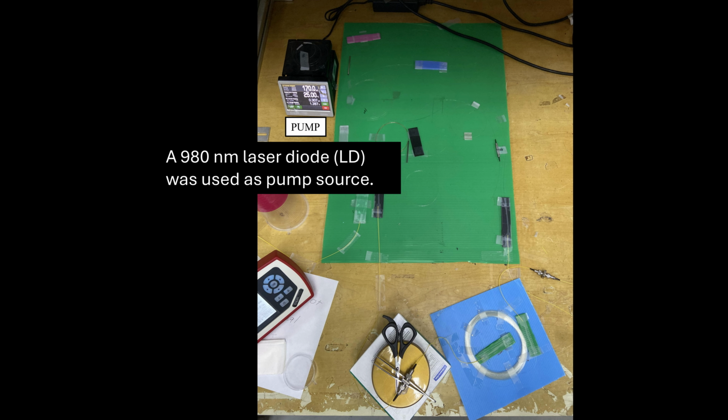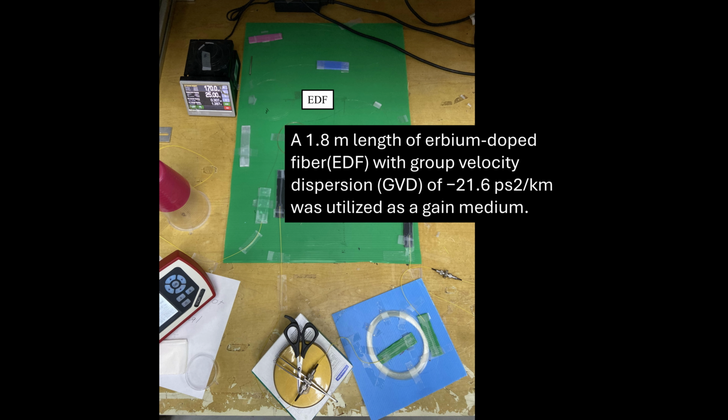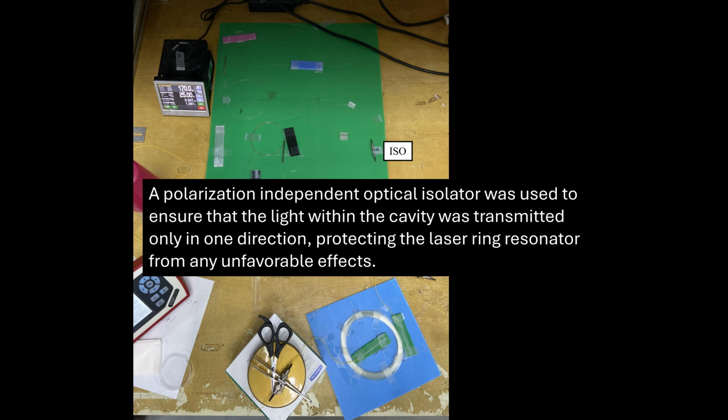A 980 nanometer laser diode was used as the pump source. Subsequently, through a 980 to 1550 nanometer wavelength division multiplexer, the pump energy was introduced into the cavity. A 1.8 meter length of erbium-doped fiber with group velocity dispersion of 21.6 picosecond squared per kilometer was utilized as a gain medium. A polarization-independent optical isolator was used to ensure that the light within the cavity was transmitted only in one direction, protecting the laser ring resonator from any unfavorable effect.